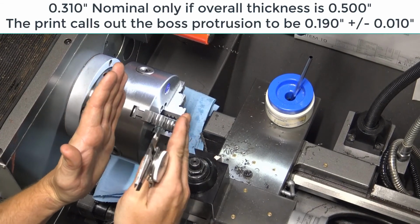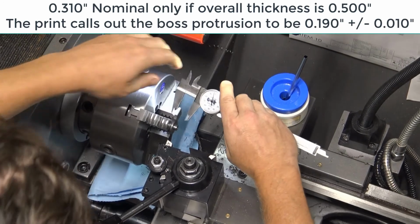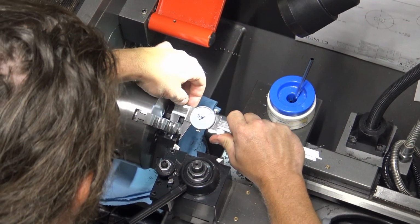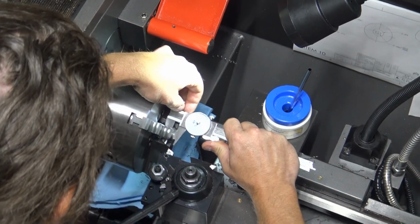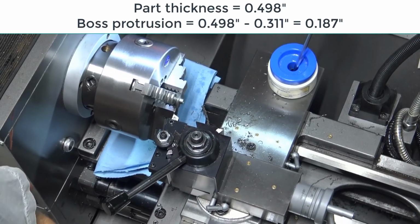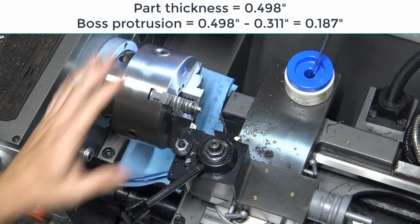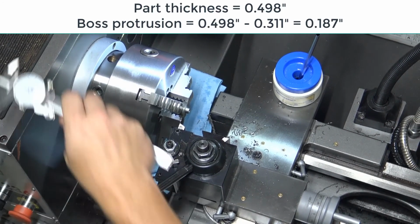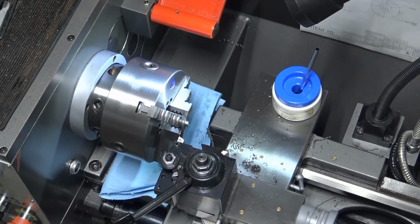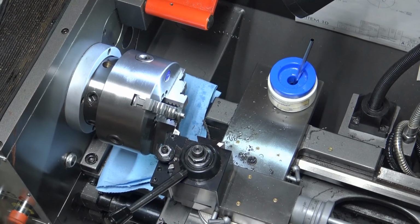We went in 190, so that should give us 310. And wouldn't you look at that, I'm at 311. I had a 10 thou tolerance on that, so I'm good there. Everything is measuring correctly, so the last step will just be to deburr this and clean everything up.